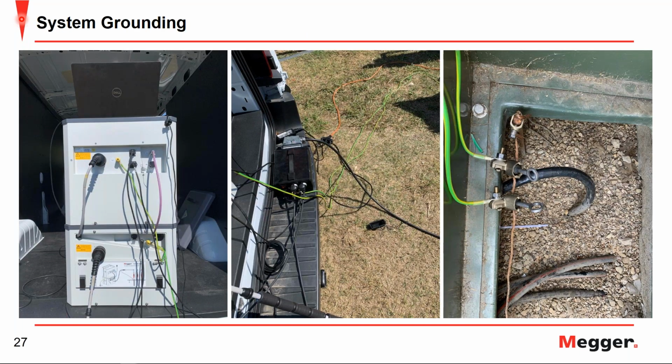Again, same as the first instance, the very first thing we want to do is connect our grounds. In this case, because we have a base set and a booster set for our cosine rectangular and damped AC capabilities, we have our interconnecting grounds. We want to make sure that we have a single point ground for safety reasons, and for the instrument and for quality measurement.